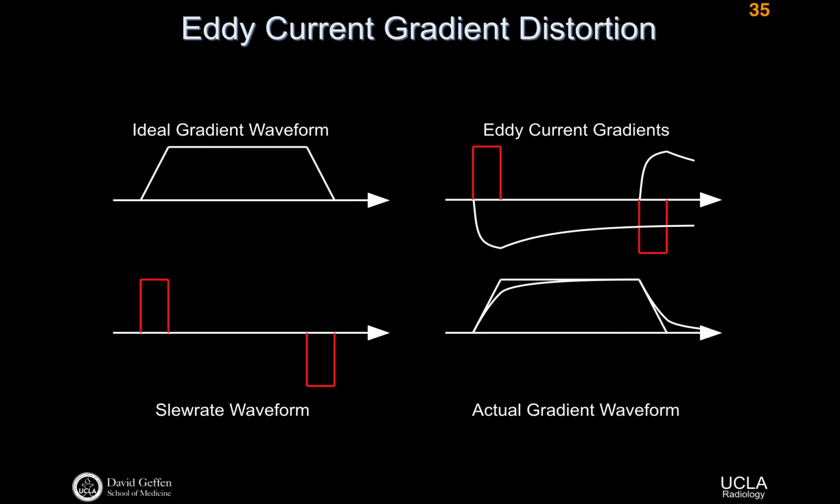And so that field superposes with B0, superposes with the gradient field, for example. And you have a target gradient that's turned on, so readout gradient, phase encode gradient, whatever. But you won't get exactly that performance that you wanted because of the superposition of this eddy current field with the desired gradient. Does that help? Or is that not your question?